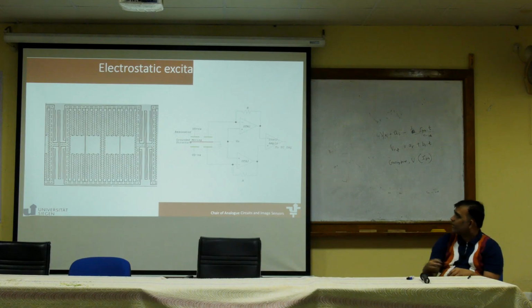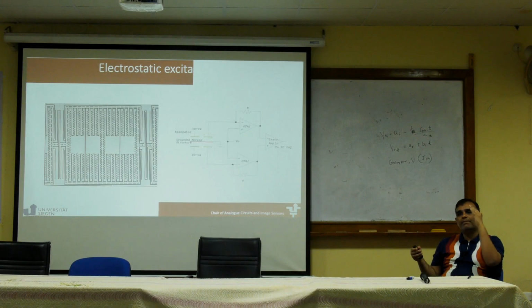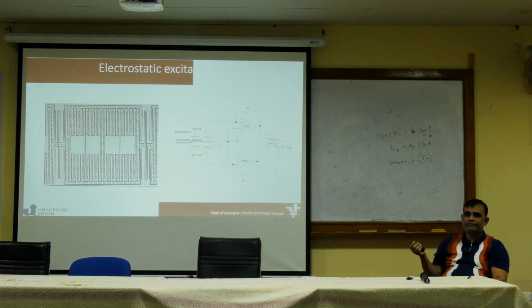Now to give you an example of how this circuit worked, remember the big resonator which I showed you earlier. So we had a moving structure which is all around, and has got all these interdigitated fingers. And that structure we have grounded. So electrically, it looks like this grounded moving structure, which is moving between parallel plates. Then two of these plates we are using for excitation. So we basically apply a force here. Okay? And we are applying a DC force plus and minus an AC force. Okay? So on one plate we have got Vd plus Va, on the other plate we have Vd minus Va.